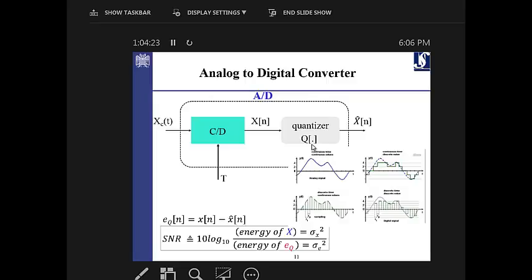Then you have to create an electrical circuit to somehow saturate the voltage at some level, linearly or non-linearly depending on your application, to map the signal from that range to a lower level. That's called level shifting in analog electrical circuits. So you do the level shifting, and when you are in a certain range which can be used by an A to D converter, then you give it to the A to D converter.